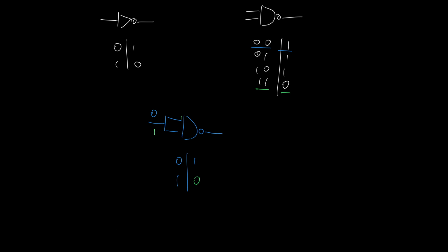Next we consider the AND gate, and I'm only allowed to use NAND gates, but a NAND gate, even just by looking at it, is equal to an AND gate followed by an inverter. And if I want to get rid of that inverter, I just have to put it through another inverter. And so in other words, if I want an AND gate, I can get that by taking a NAND gate and putting the output through an inverter.